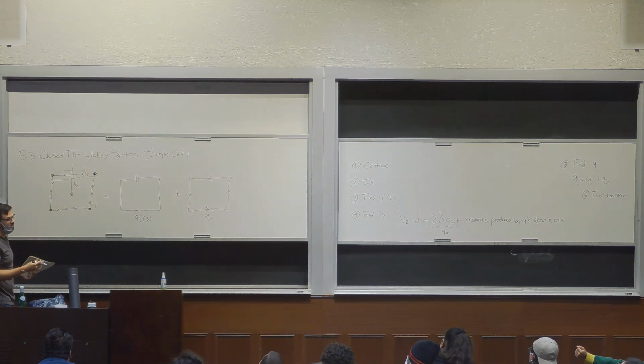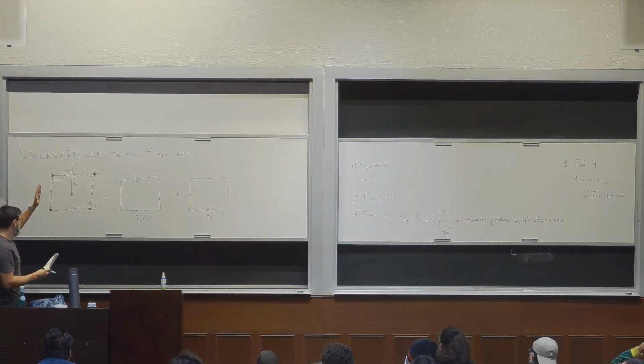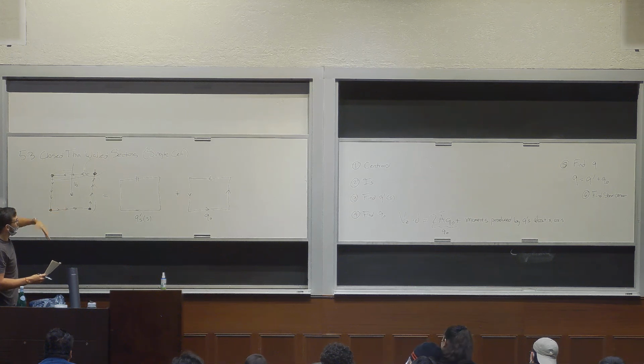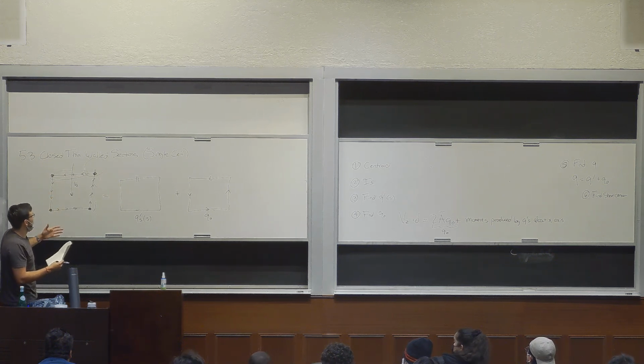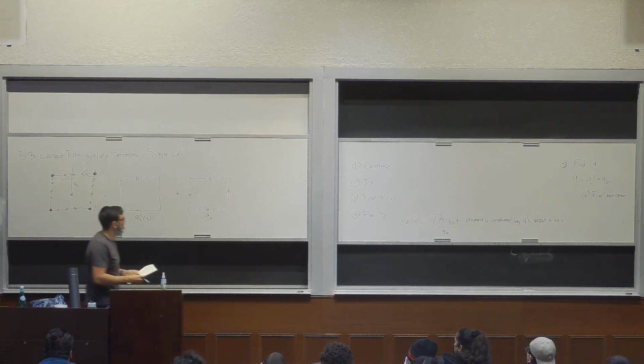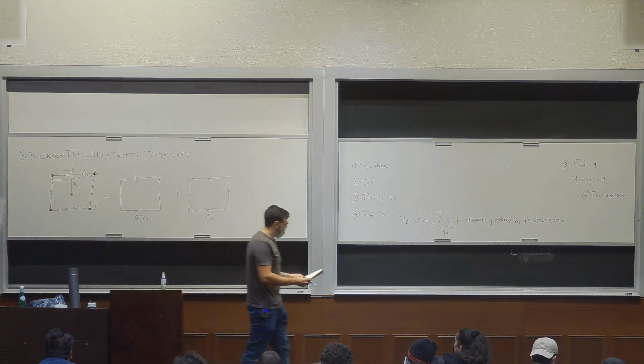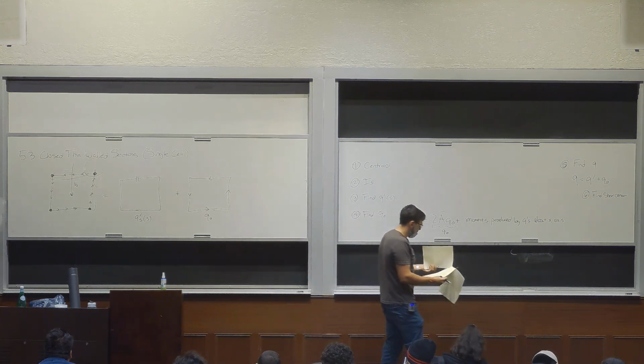It wouldn't twist. If it wasn't right through the middle, if it was to the right or to the left, this cross section would rotate a little bit. And so the shear center is that location y about which Vz should be applied to reduce this twisting deformation. This might be intuitive here because it's symmetric, but if this was not symmetric, then Vz has to be placed somewhere else so that it doesn't twist. That's the whole idea behind shear center. So let's do an example and we'll get out of here.